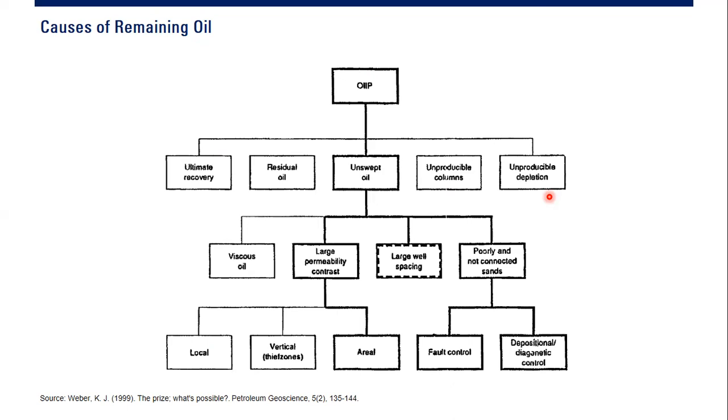And because it's already at low reservoir pressure, we cannot produce it, because in our operations somehow we have high system pressure which leads to high wellhead pressure. So the well cannot lift the oil because the reservoir pressure is low and the system pressure is relatively high, such that we cannot drain the oil and move it up to the surface. And you can always check it and compare it with your experience.